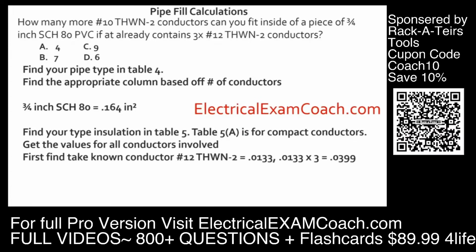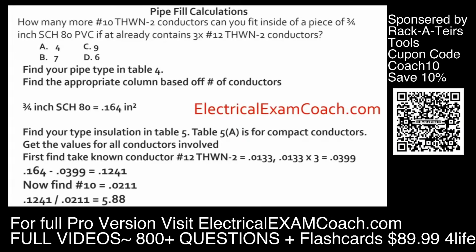First, we're going to take our number 12 that we already have, multiply it by the 3 that we already have, and that gives us this value. Then we're going to take our total available to fill minus what we already have, and that gives us this for our remaining left to fill. Then we just take that and divide. We divide that out and we find that we can fit 5.88 conductors, and in this case it is 0.8 or larger, and we will round up to 6.